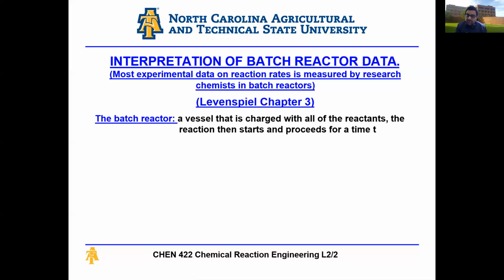kinetics, right? So usually if you want to understand the kinetics of a reaction, most of the time you'll do it in a batch reactor and look at the change of concentration with time, maybe look at the change of conversion with time, and this is how you really understand the reaction kinetics, okay?